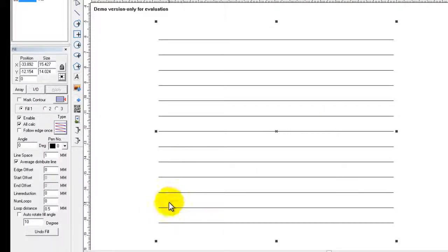However, when the laser processes this first line as it comes across, instead of jumping up to this next line and coming back this way, which in turn saves us marking time and is more efficient, it's going to go down, it's going to stay on. When it's done marking this line, the laser is going to turn off. It's going to steer the beam location back to this point and start again. So it's jumping back to the beginning each time as it does each line. This fill is sometimes important for specific plastics and controlling heat.